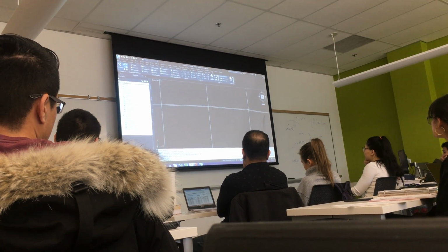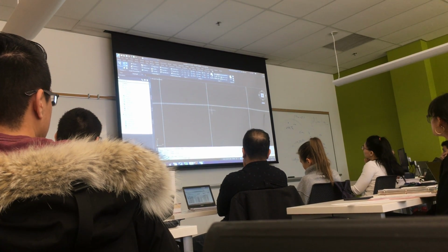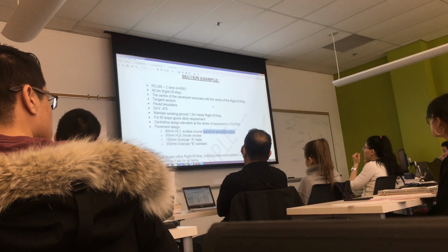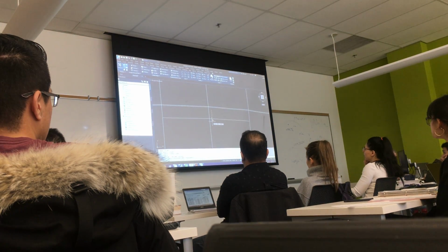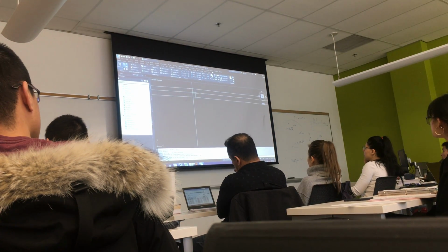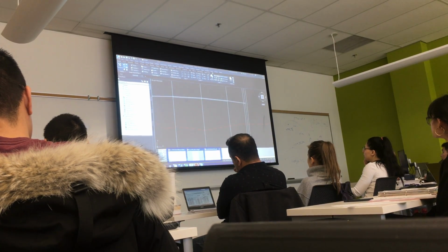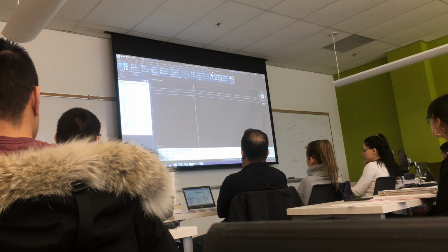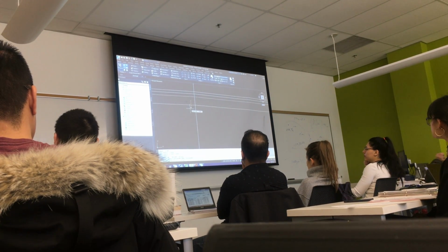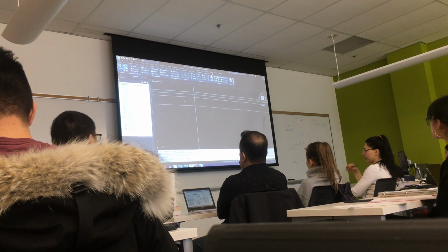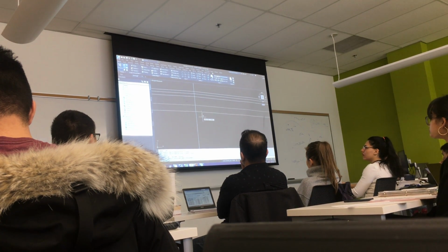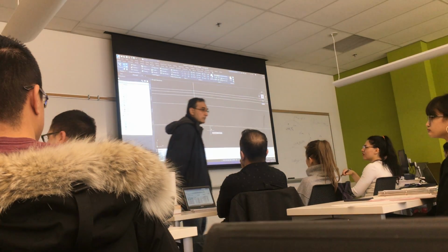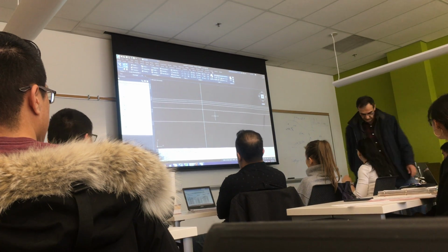Then I'm going to copy the bottom one. And I'm going to go down 50, right? According to the design, I need 50 millimeters. So 0.05. So there's the two layers of asphalt. Okay? Then I need the layer of the base and sub-base. So I've got 150 and 350. So I'm going to make a copy of the bottom of the asphalt, straight down to 0.15. And then I copy this straight down 0.35, I believe. Okay? So there's the thickness of each material.